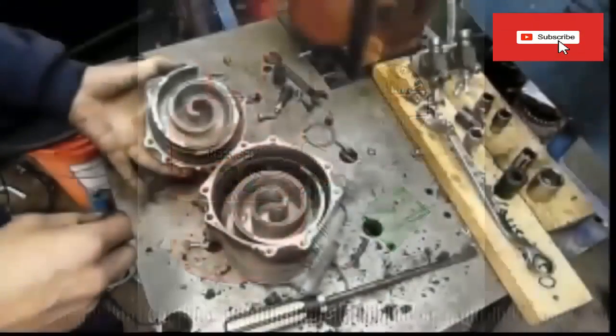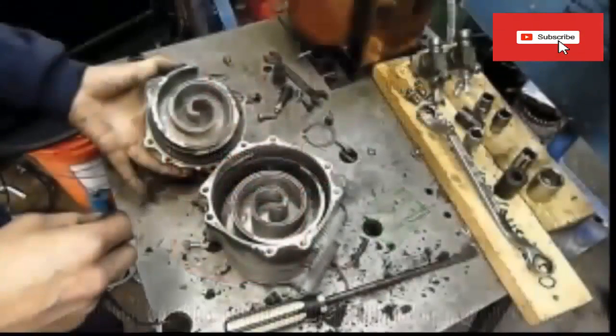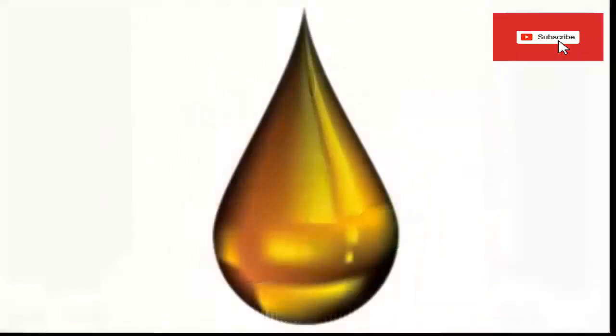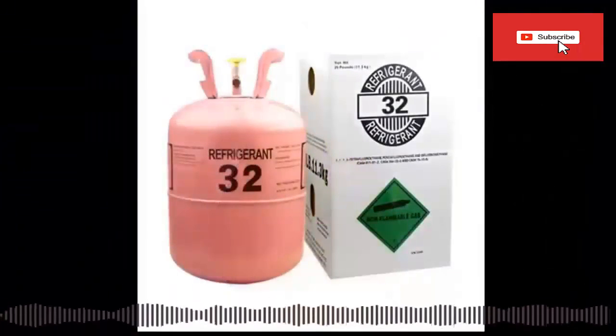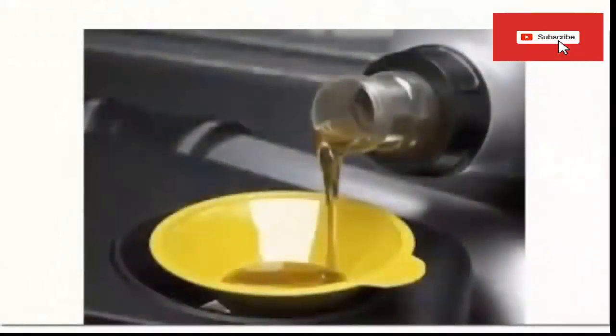If a compressor works with higher discharge temperatures than it was designed for, it will quickly fail. Also remember that the viscosity of the oil refers to the resistance that this liquid has to flow or deform. If the temperature increases to inappropriate values, the viscosity decreases. This causes the oil to not stay at the points where it should be to achieve lubrication.